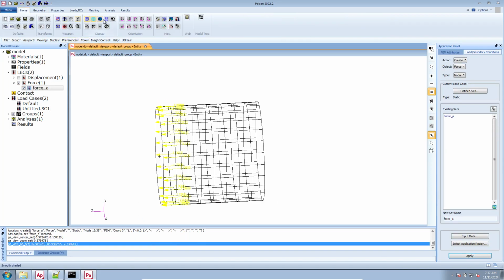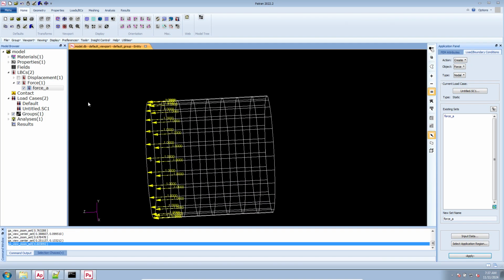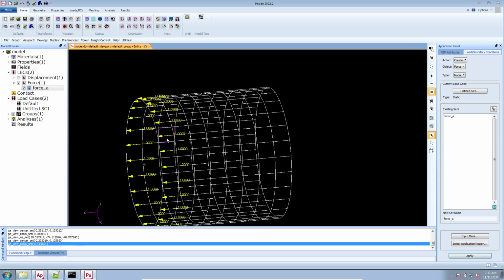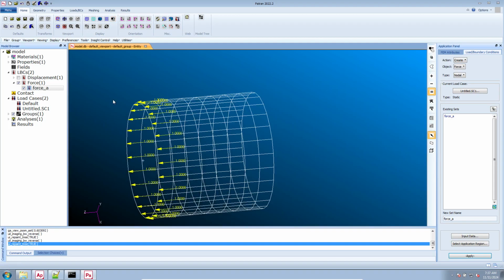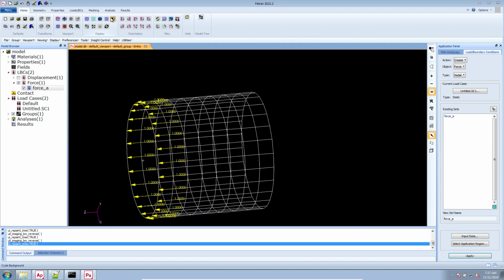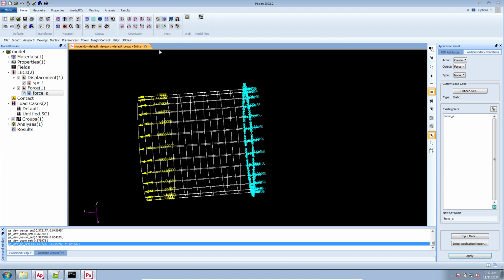If you go to home and click on the background color, this will help you contrast and differentiate the different colors. If you notice, a moment ago with the white background, I couldn't read the values of the legend, but if I change the background color to a darker color, I can tell what's going on here. And our displacements, let's turn that on with the checkbox here on the left. So here's my cylinder, I'm just pulling on it.